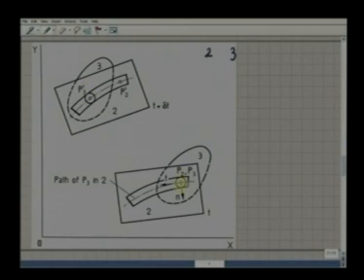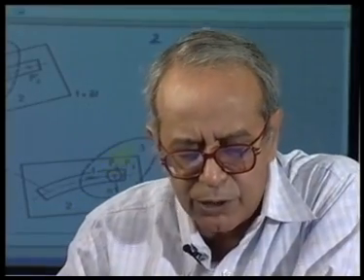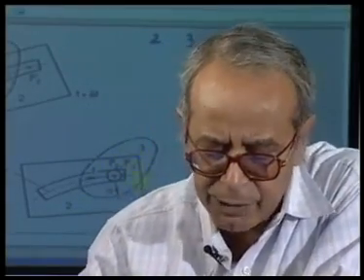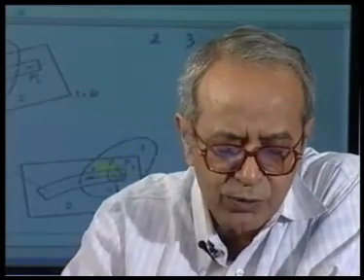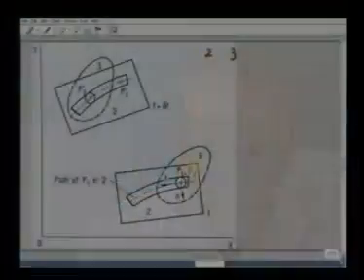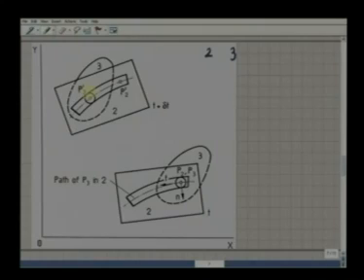And the point P2, which belongs to body 2, that is a point on the center line of the slot, has come here, which I call P2 prime. So P2 and P3 are the two instantaneously coincident points, P2 belonging to body 2, P3 belonging to body 3. During time delta t, P2 has moved to P2 prime and P3 has moved to P3 prime.